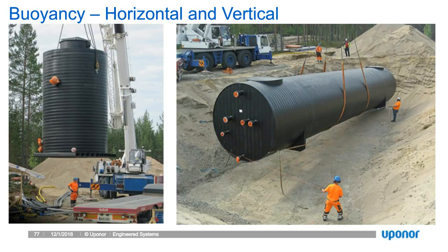And then we can rely on the soil column around the structure or above it to provide additional buoyancy anchor. For vertical applications, we would extend the base plate to capture more soil column and can do that up to a 14-foot shipping width. For horizontal systems, we rely on a strap and anchor system. It's fairly straightforward.